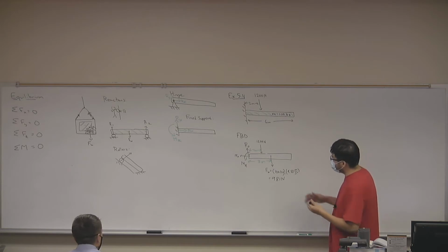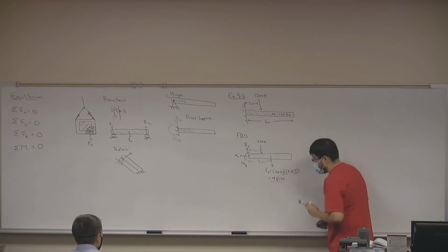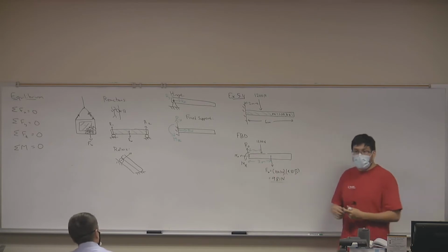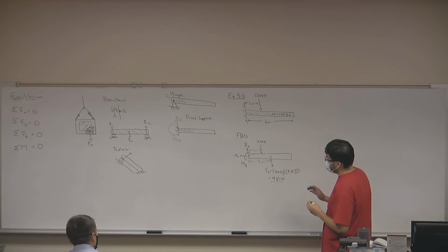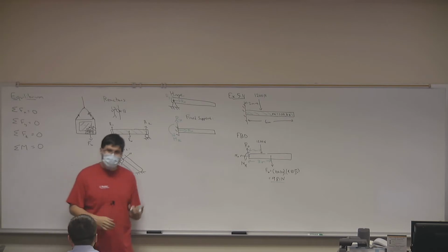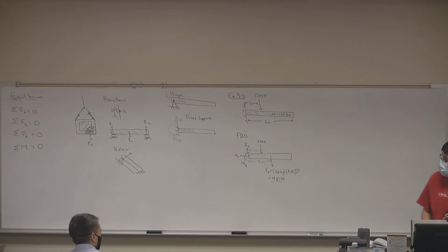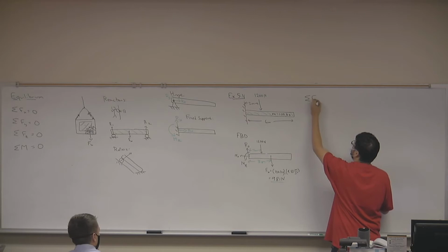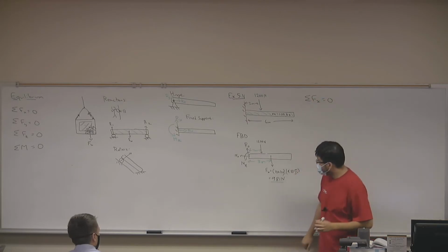And what is the problem? I would like to know all of the forces acting on this system. Now you already found one force, which is the weight. Good, you found it. But now we can find our reaction forces, right? So how can we find the reaction forces? Well, if this is a static system, we apply equilibrium. Sum of forces equals 0. And just to give a little bit of an illustration on why the X reaction goes to 0, let's just start with the x direction. Sum of forces in the x direction equals 0. Looking at the system, what x forces can you identify?